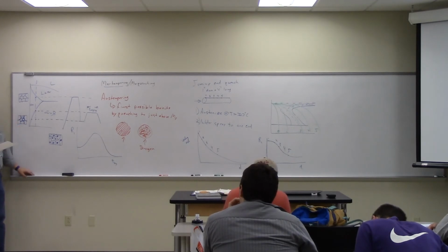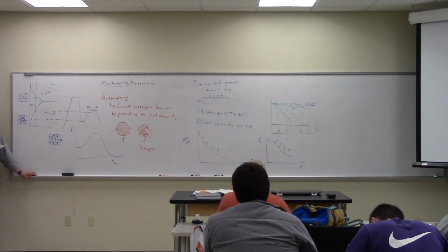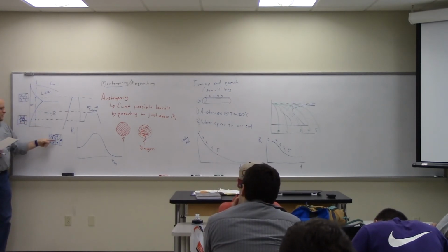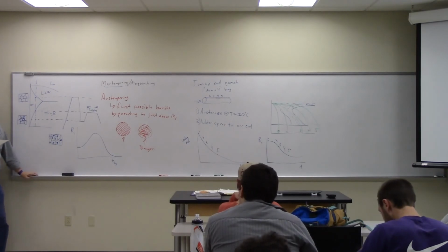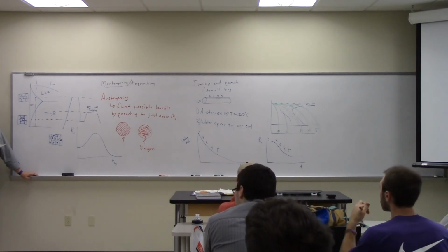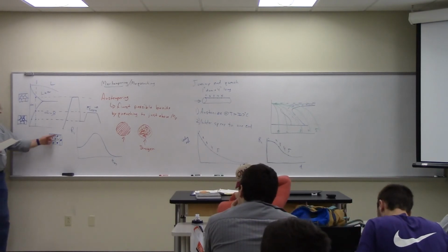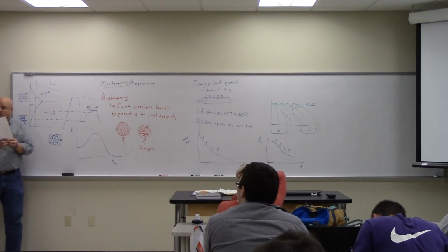So if you're doing it the right way, will you still get beta at the grain boundaries? Yeah, you'll still have it at the grain boundaries. You can't avoid it, but the point is, you'll do it by staying right here, just below that temperature. Then you enhance the opportunity to achieve beta anywhere uniformly in the material. But at that point, there's not that much drive for there to be beta at all. Right, so they're just tiny little specks. But as I cool it down, those tiny little specks, now having nucleated, will grow.